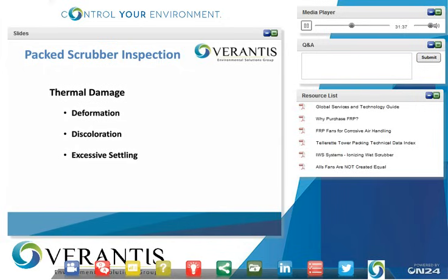Discoloration, obviously. If you see any type of darkening of the packing, polypropylene is typically a whitish, clear whitish appearance, and if that starts darkening, that could be that first indication that there was either some type of thermal upset or there's a periodic upset that's occurring.